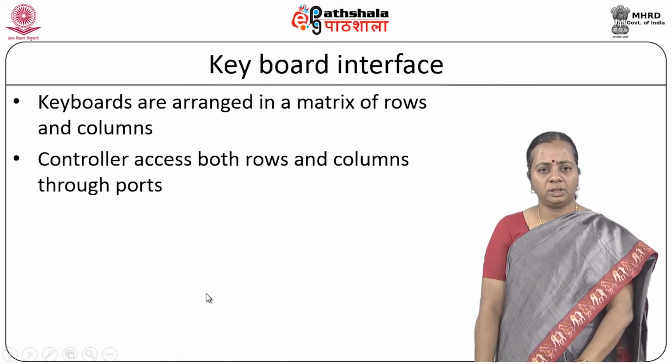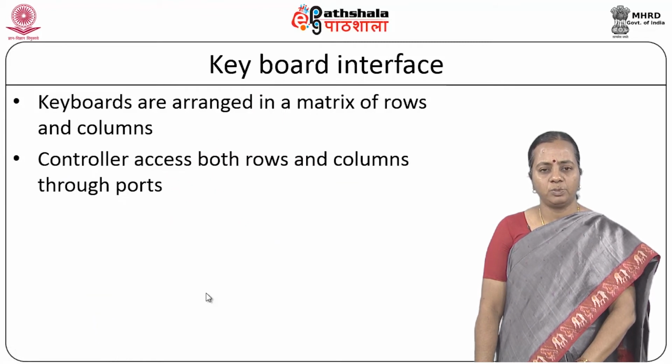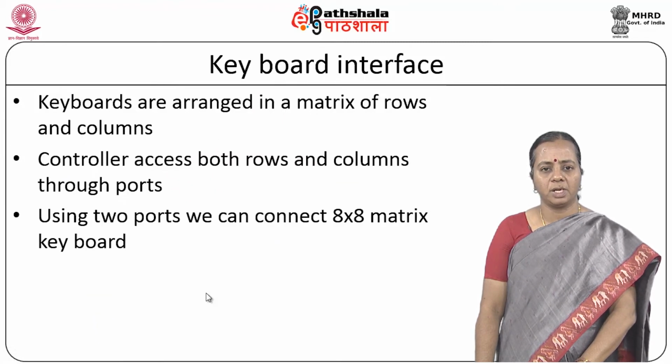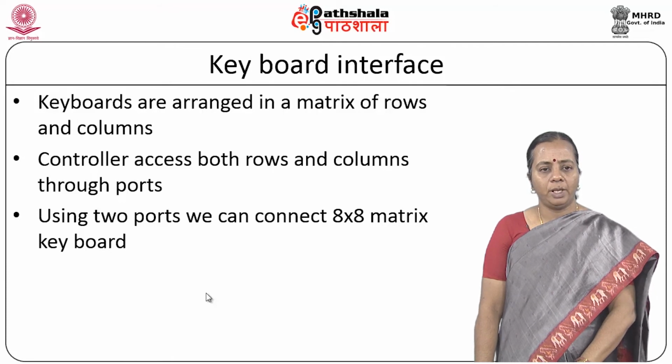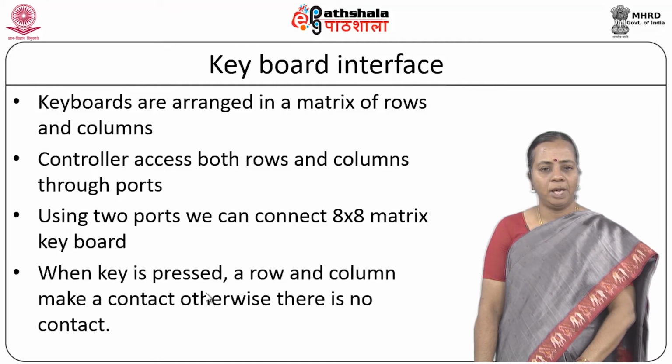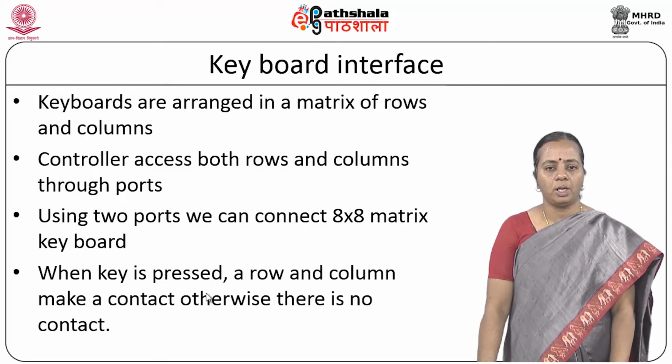So, the next one which we wanted to make as the input interface with 8051 is nothing but keyboard interface. So, when you are looking at the keyboard, here I will be constructing the keyboard like a matrix of rows and columns. So, when I am looking at the matrix of rows and columns, in the sense if I have 4 rows and 4 columns, then 16 keys I can make out.